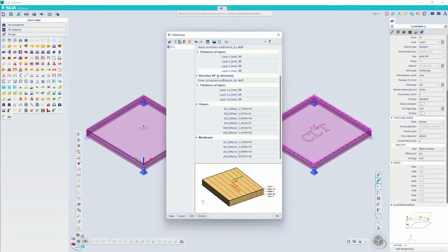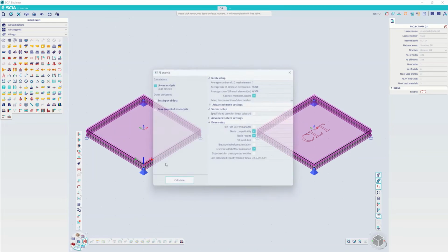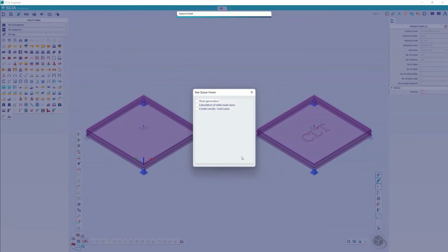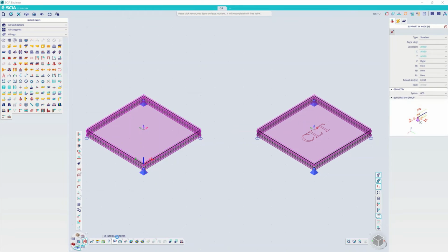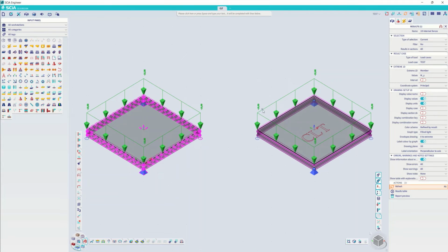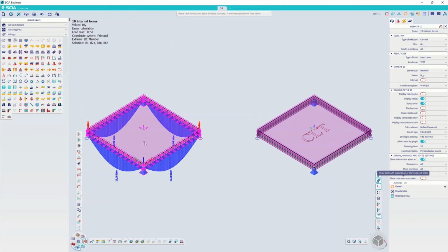So the X direction in this case has 4 layers. The Y direction has 3 layers, which means we will have more bending stiffness in X direction, at least for the slab on the right-hand side. And I will show you how this influences the results, because now we expect an equal bending moment on the left-hand side for all those 4 steel beams, because we have an isotropic slab on the left-hand side. And you can see this because all values are close to 19.